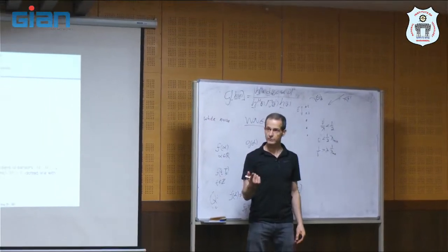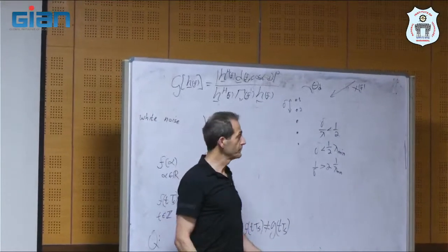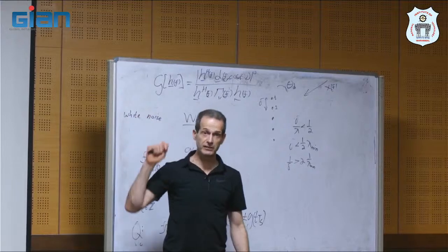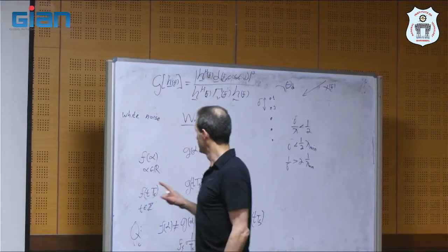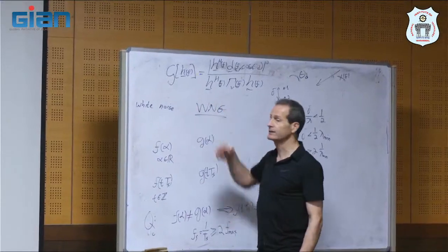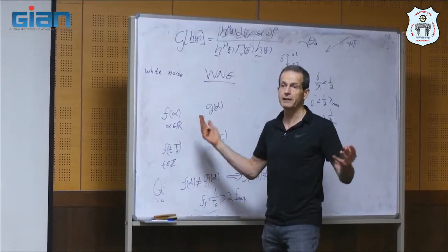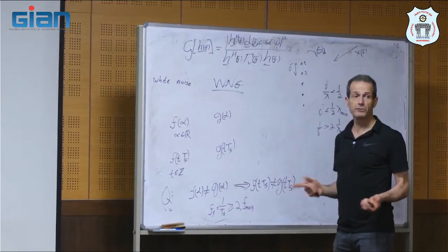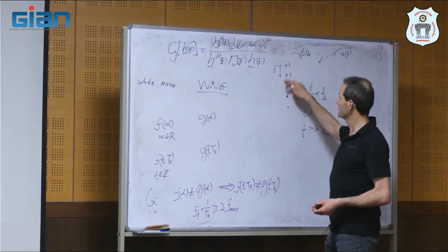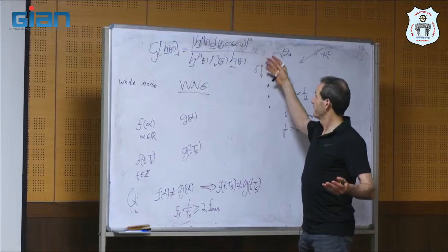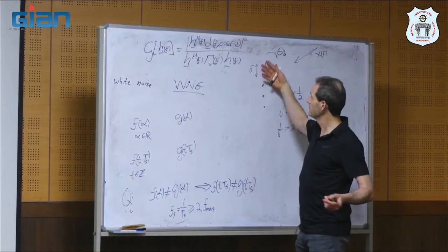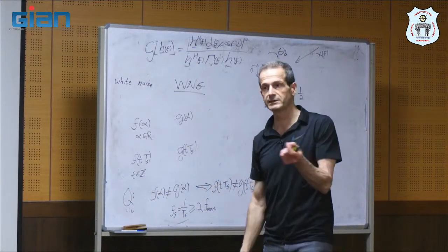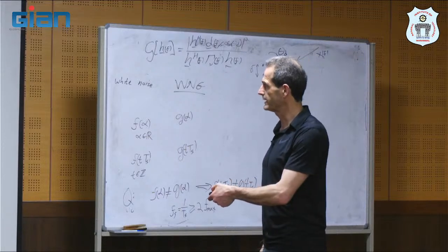The variance is reduced by a factor M, which means that the white noise gain achieved by the beamformer that maximizes it, the maximum possible white noise gain, is M, the number of sensors. When you take uncorrelated noise and take the average in the delay-and-sum, it reduces the variance by a factor of M. We know that from statistics. It's very simple.